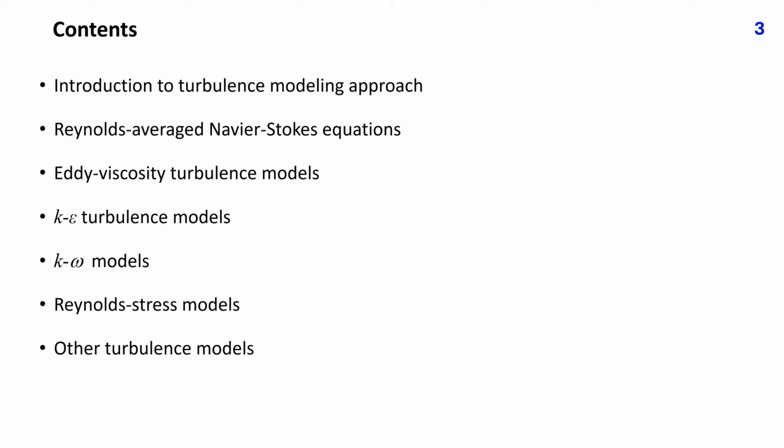To compute the eddy or turbulent viscosity, we need to determine the velocity and the length scale of turbulence. Many turbulence models require the computation of turbulent kinetic energy, from which the velocity scale is determined. We present the exact equation for it and the models for terms which include additional unknowns.